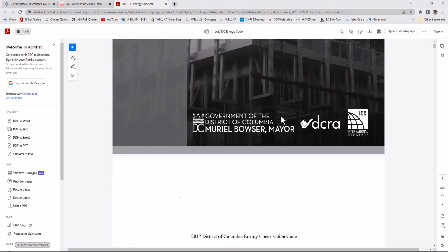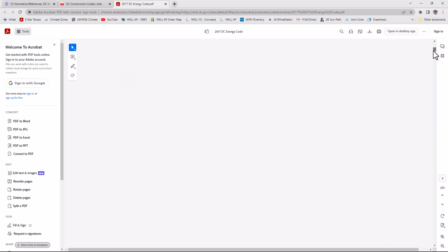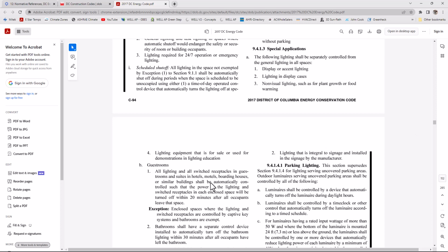All right, so in here we go. So why do we use the Energy Conservation Code? Mainly because in the beginning of the design, you don't have the envelope values. You don't have the thickness of the walls. You don't know the U factor. You don't know the insulation values of your building, because they are still developing your building. So you're not gonna wait for the architect to provide, hey, here are the insulation values for your building.